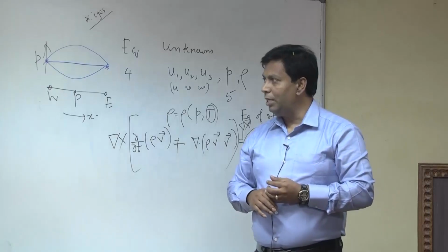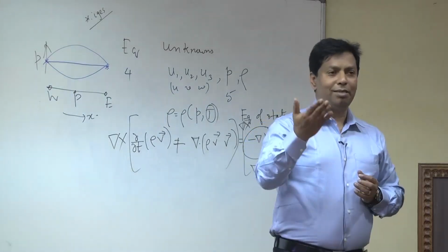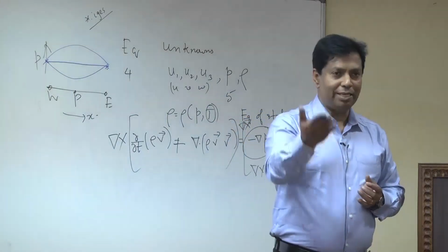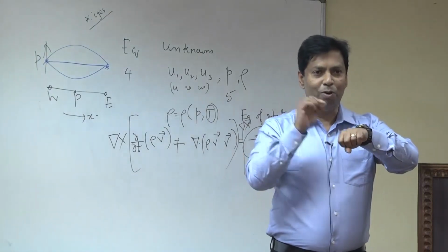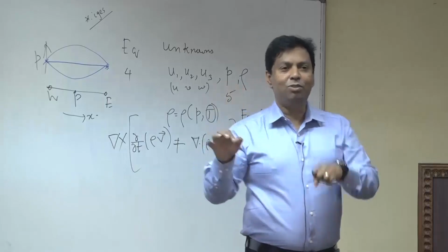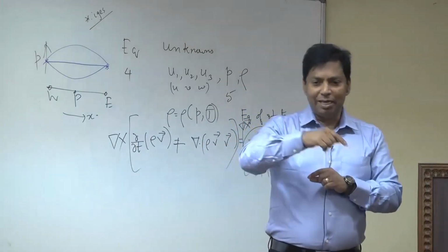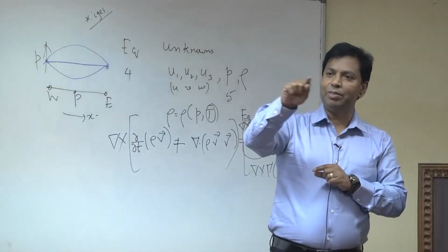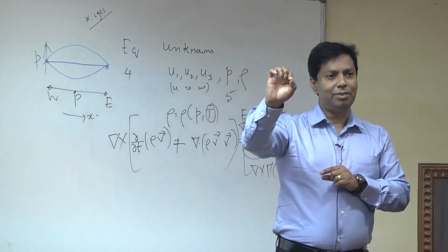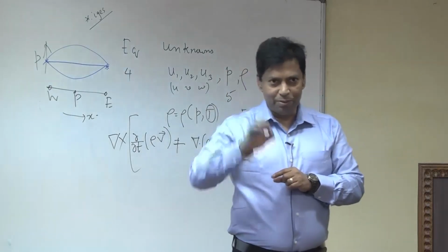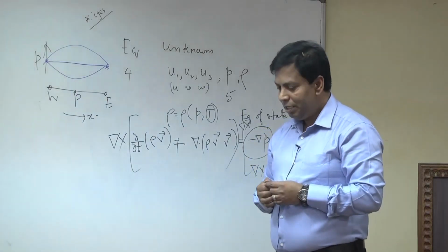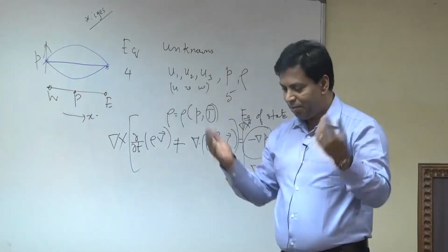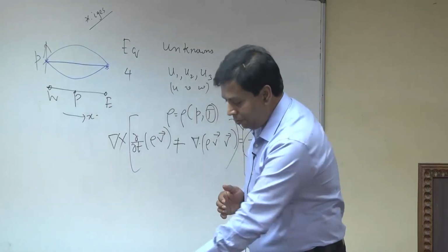So in that way, he just told me, simulate 10 iterations and see how much real time it takes for a single processor, then for a double processor, and draw a curve, and where the curve has converged, take that one. Okay, this is how many processors you need. So that is very important. It is not always good to use the maximum number of CPUs.